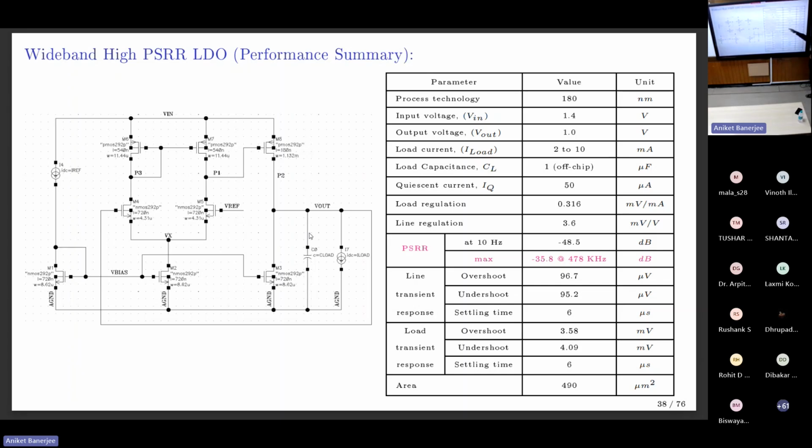There are no iterations involved. Just one time. You master the technology, meaning how to use the lookup table methodology, like how you mastered square law. You master the gm/ID based lookup table methodology. Then you apply it to the circuit, knowing what the circuit wants. Knowing what the circuit wants, you get all this performance done in one iteration. So this is the methodology to be followed.